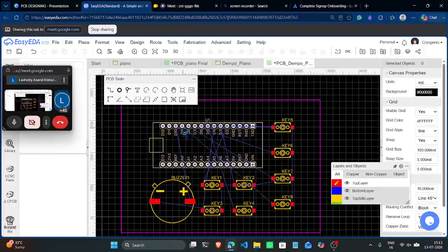It is indirectly telling you that you need to connect this. What is the purpose of this? While doing your routing part, while you keep traces, you might mismatch other pins. Instead of connecting these two, you might end up connecting this with pin 4. It will happen when you deal with thousands of connections.